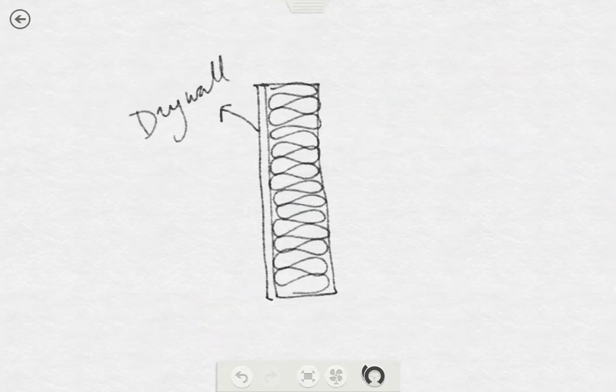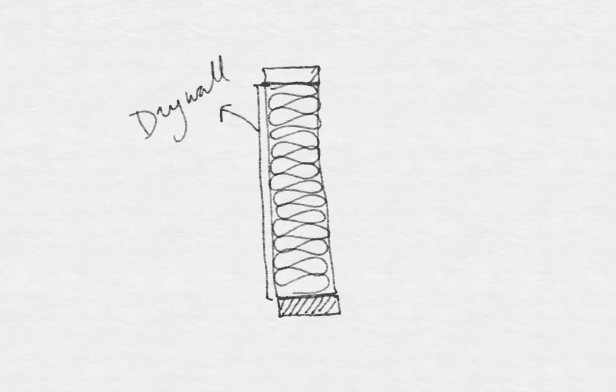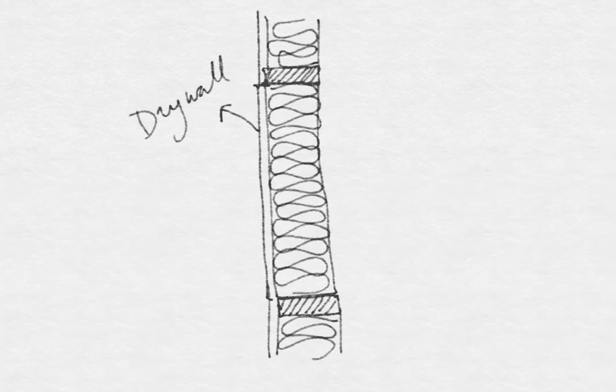And here, what we can see in your detail is that we have horizontal elements. Then here we continue with the thermal insulation, and we continue with the thermal insulation here, the drywall. So those horizontal elements are to make the frame, to provide the frame wall with stiffness, okay? Because if we don't have a horizontal element, probably they will bend. So that's why we need these.